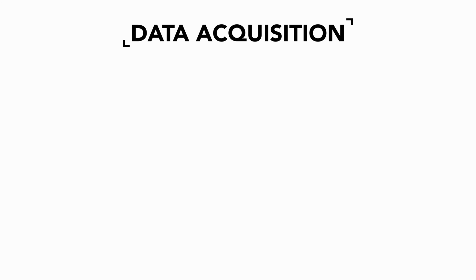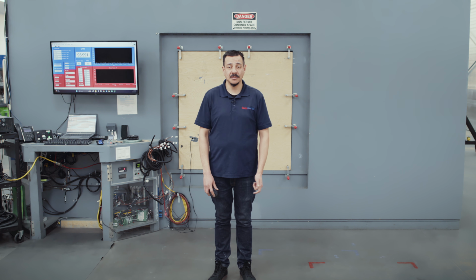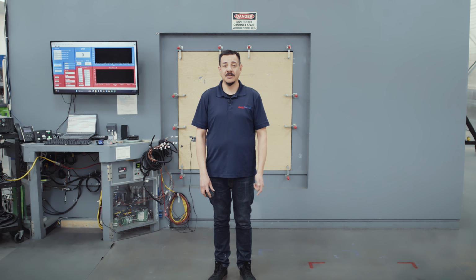For our data acquisition system, we use National Instruments hardware and we use LabVIEW software with our custom airflow programming, using all the data we acquire via our transducers, thermocouples, and pitot tube. The acquired data then goes through the hundreds of equations from AMCA 210 to calculate the airflow.